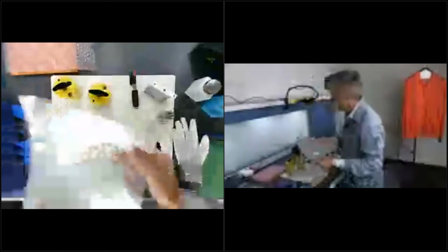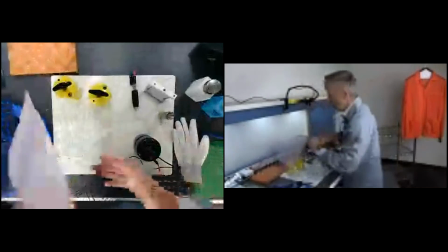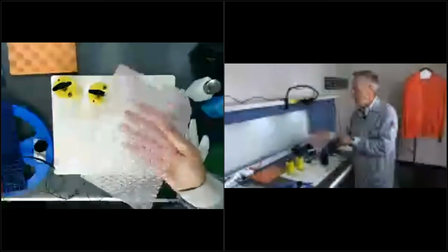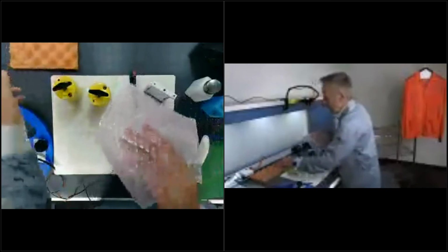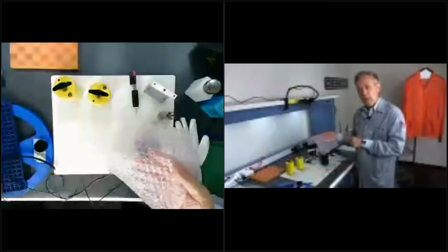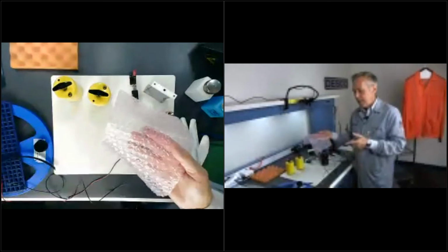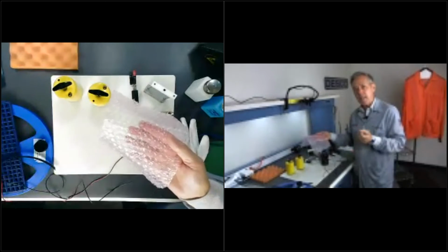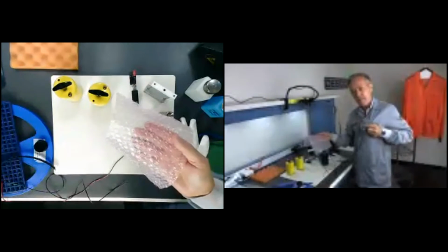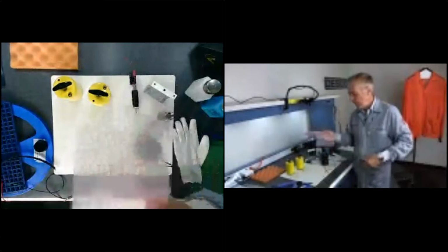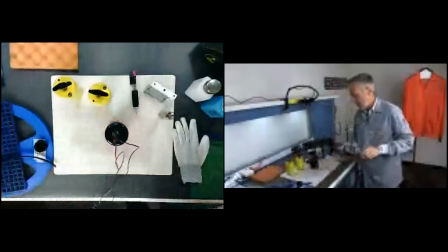I might test a couple other little things while I have this. Here's a typical sheet protector or shop traveler. You'd want to measure foam materials. Now, one of the reasons I mentioned things like bubble wrap, pink foam like this, for instance, and the importance of testing these periodically is because these types of materials are almost never identified. The standard requires that I identify my ESD materials, typically with that reaching hand, like the one on my smock here. So you're never going to see this kind of stuff identified. So you want to be making regular periodic verification measurements of materials like this.